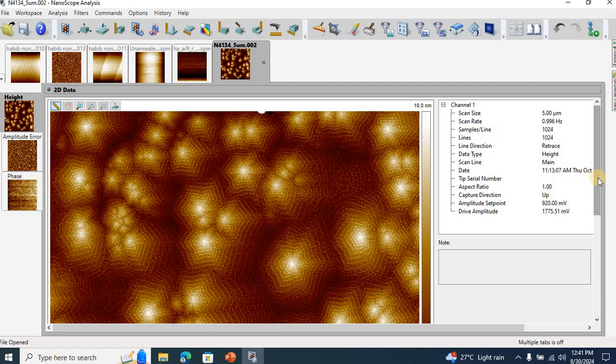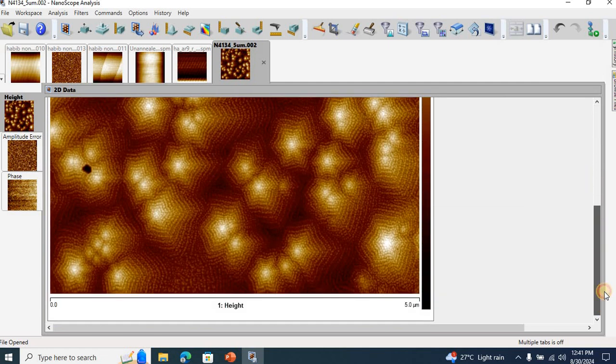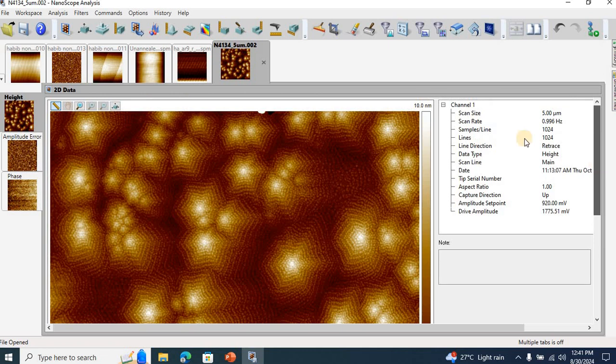We perform them using an advanced version of molecular beam epitaxy, which is called metal modulated epitaxy, in which the nitrogen flux is kept constant while modulating the metal fluxes using a shuttering scheme. If you are interested in metal modulated epitaxy, you can study some literature about it. And this technique was introduced by the wonderful Professor Dr. William Allen Doolittle.